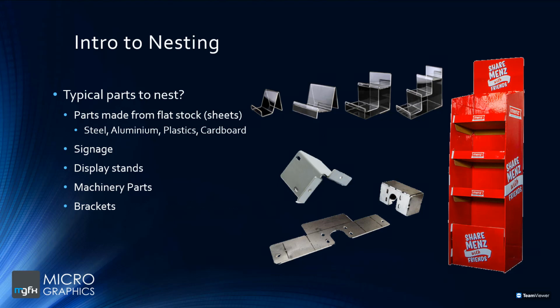Any part that is made from flat stock or sheets can be nested with other parts of the same material spec. So basically this would mean that as long as the material type is the same and the thicknesses match, those components would all be put onto the same sheet. And if there are multiple material types or thicknesses in your design, those would then be split out across the relevant material specs for each component.